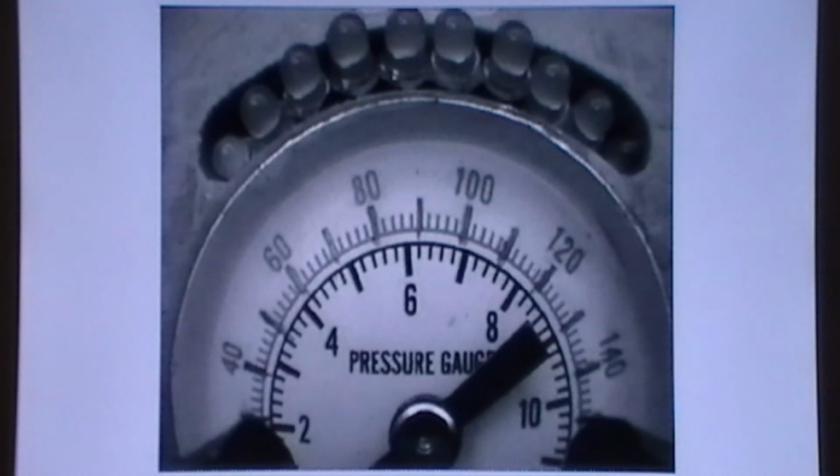The pressure gauge measures the water pressure near the entrance point to the water laser tube. Water pressure is noted to be nowhere near proportional to water speed. When the device is turned so that the water flows to the east, the lower right direction indicator LED is triggered, and when it's turned so that the flow is to the west, the lower left LED is triggered. The curved array of LEDs at the top indicate water speed and are driven by the current generated in a coil by a magnetised impeller on the inside of the copper tube that's mounted in the water return hose.